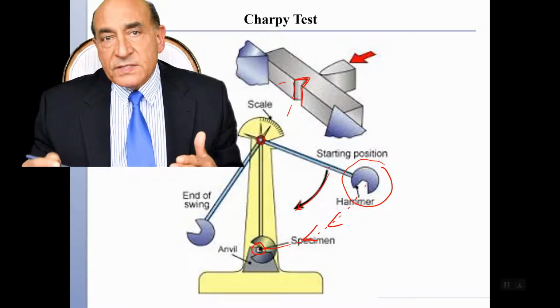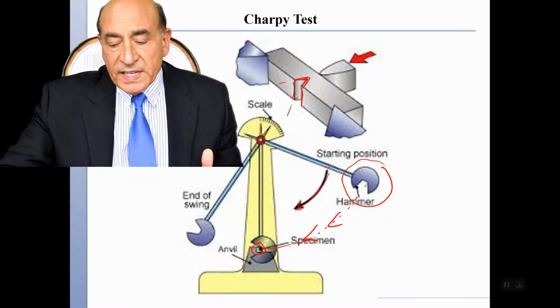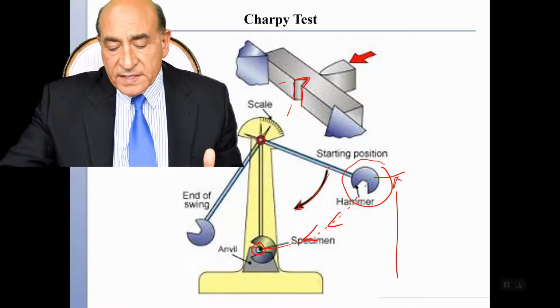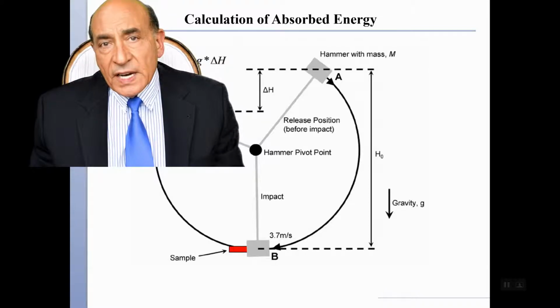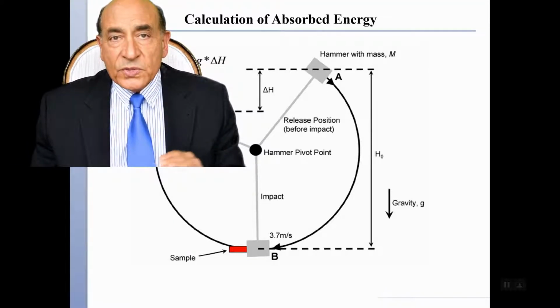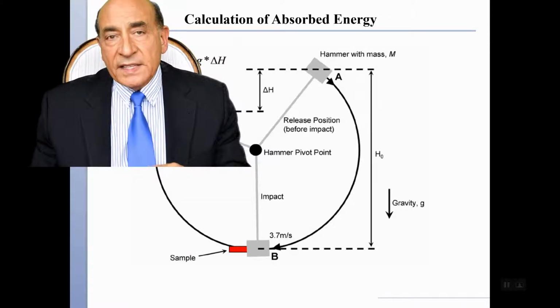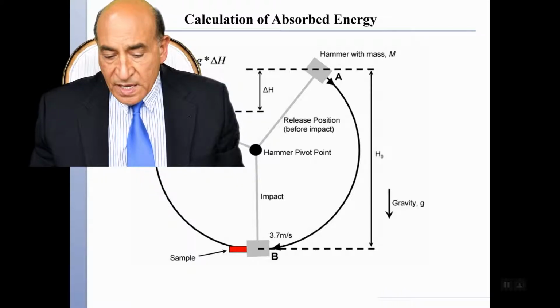The test is performed on several samples, some of them with variations of this height. Some samples do not undergo fracture, but others will fracture, and therefore we could determine the critical height that causes fracture of the sample.